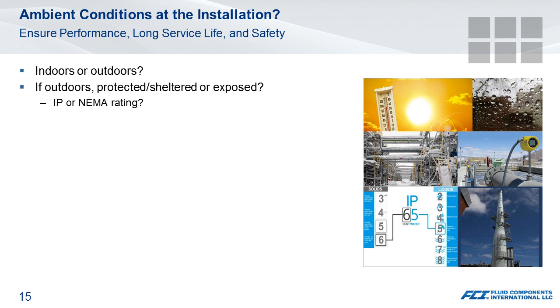And in a process environment, particularly in refineries, chemical plants, oil and gas, hydrocarbon related, is it an explosion-proof required application? And if so, both what class and what divisions will it experience? Does it need to meet, and also which country's standard?